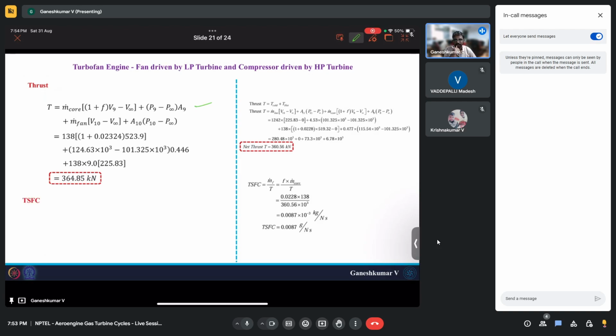Similarly you can do the TSFC calculation, and it's very easy to predict by now. We are using more fuel. So whether the amount of fuel that we add justifies the amount of thrust that we generated is what is given by TSFC. In the TSFC calculation we will get to know whether it is fuel efficient or not.